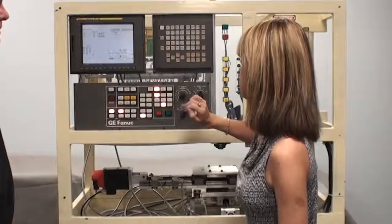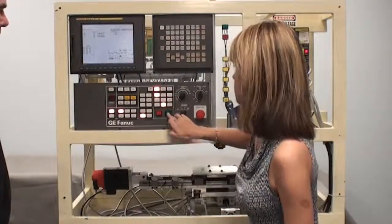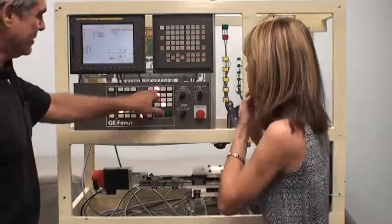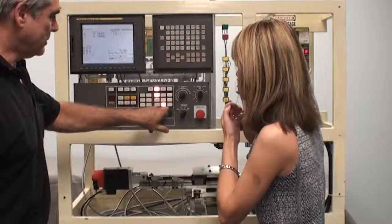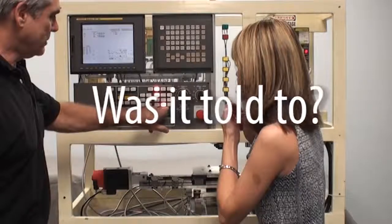So here is a scenario for you. You walk up to a machine and attempt to jog the axis using a jog button, but nothing happens. Where do you start looking for the problem? It's very simple. Remember to ask this question: was it told to? This is a very important question. Was it told to? Pushing that button activates an X address.